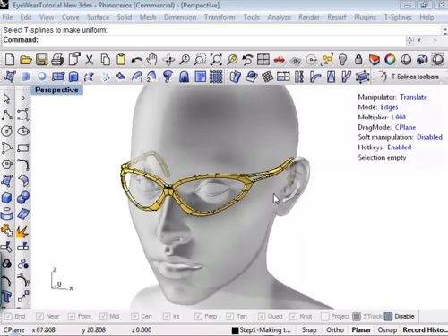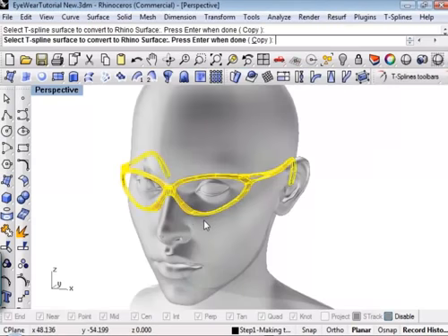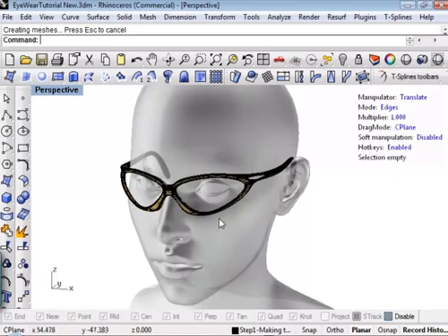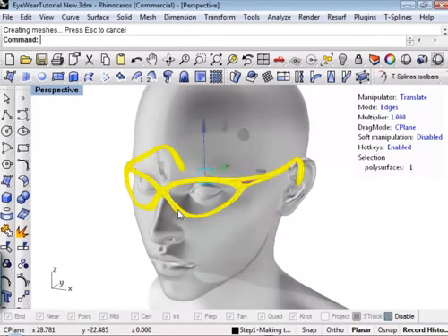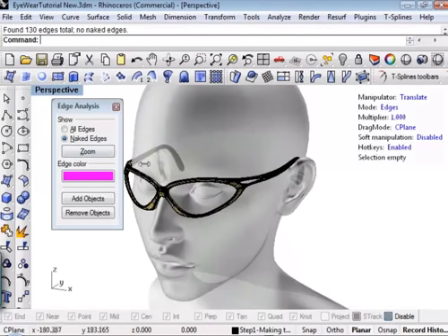Yeah, Silo is great and all, but it doesn't convert to NURBS. You have to use something else to convert to NURBS. If I want these glasses to be NURBS, this is the thing that you have to keep in mind. I right-click on the convert button, I click here, and I get NURBS. This is now a watertight Rhino polysurface. If I check the naked edges, it's got none. So this is bomber Rhino NURBS data. You can see this SLA, all that kind of stuff.